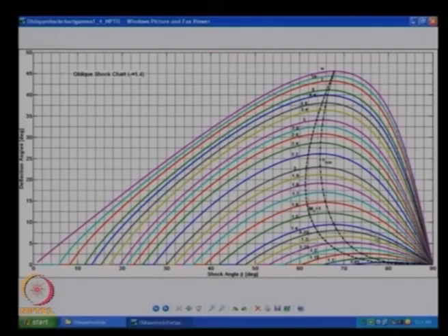First observation we are making. Okay. We will make more observations. I just wanted to plot this, I do not want to use this plot to explain things, I will go and draw this on the board and explain things. Okay. But one more thing to note, it has a peak value for every Mach number and above that we cannot get a solution for beta. Okay. That is what you are having, and beta does not have a value below a particular Mach angle, below a particular angle, it so happens that it will become Mach angle, we are going to look at that now.